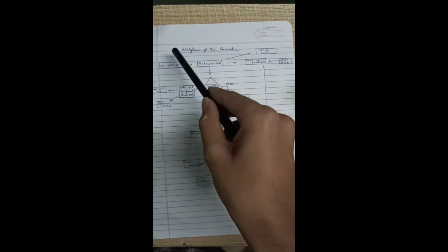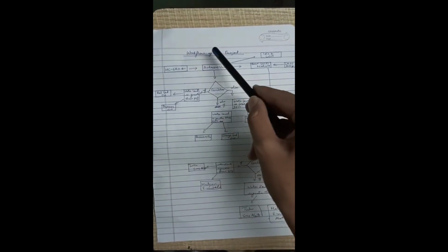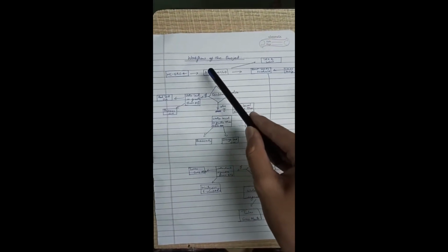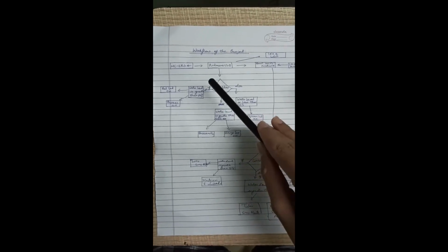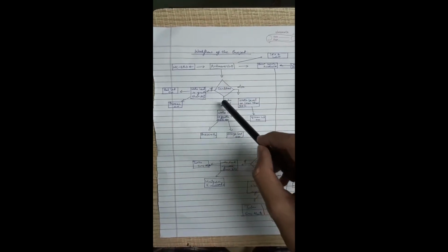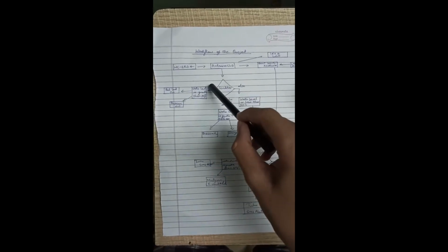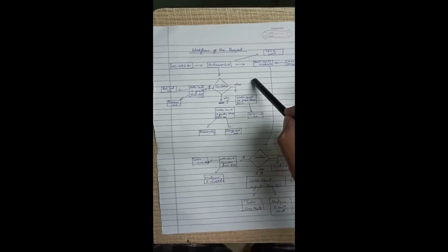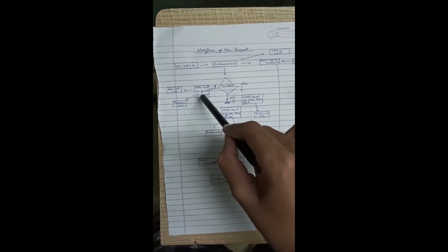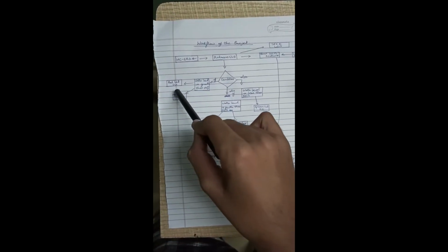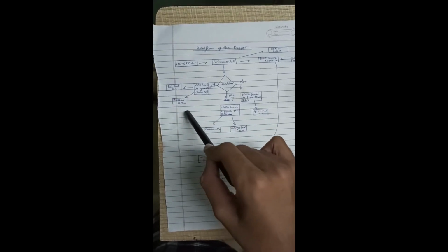Now the value that it collected will be sent to the Arduino Uno. The Arduino Uno will convert the distance taken into a percentage and will be making three important conditions: the if, else if, and else conditions. In the if condition, if the water level is greater than 80%, the red LED will be on. With that, the buzzer will be buzzing.